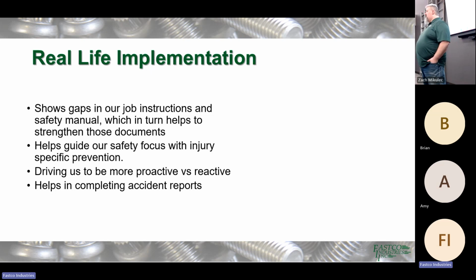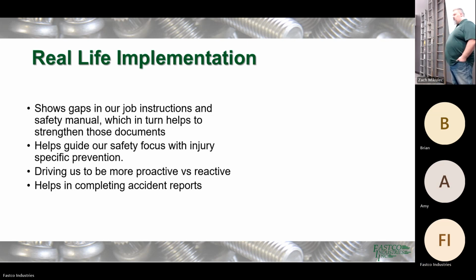If you want to set that, you can, but really what this RPN is helping us do is prioritize: this one's a really high RPN, maybe we should focus on that before it gets out of control. I remember my AIAG class, they say don't really put a requirement on RPNs, because some people will start pencil punching it to get lower. So use those numbers to help point out your problem areas. Use them like they're supposed to be used, not to get them lower, but to find out, maybe we should look into this area now instead of this area, because we seem to have this under control, but this one's kind of going out of control.